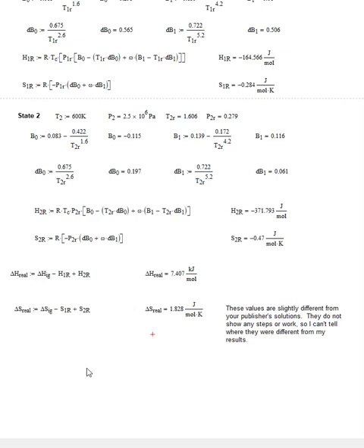And so this pretty much finishes up the subjects that we have covered in Chapter 6, where we've taken a process and have gone from the real state to the ideal gas state, done the ideal gas change, then gone back up to the real state to get the actual delta H. And we did this using only heat capacity data and equation of state information. If you think about it, that's kind of nice. That's pretty impressive that we can do this.